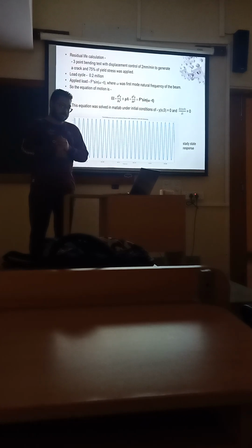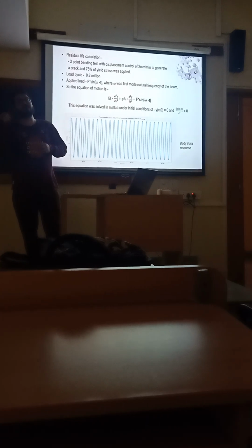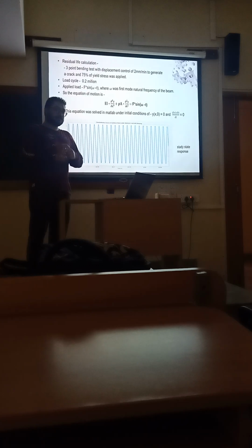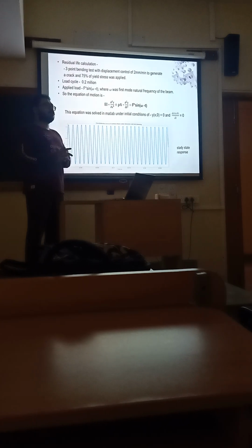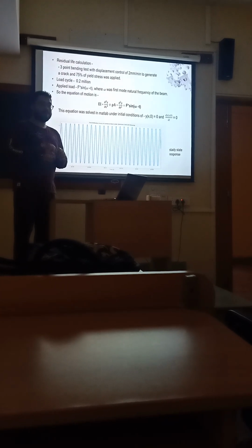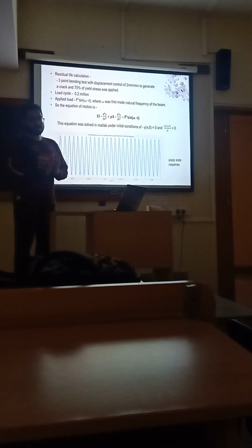But the problem with that is you cannot apply the same theory on a larger scale, for a larger structure, for a beam or a column or a plate. This is problematic, because to propagate a fatigue loading or to fail a structure in fatigue, you need one crack, particularly one crack which should propagate rapidly and then it will fail.